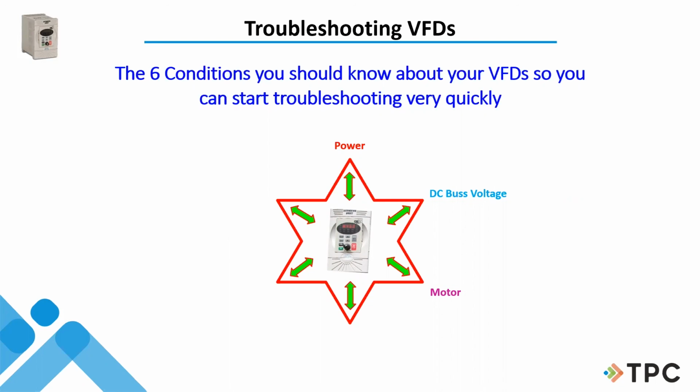And just remember, most VFDs do not like a megger. Don't put a megger on the back end of that drive, or you'll ruin the drive. You're going to have to disconnect the motor wires from the drive if you're going to check them at the drive. And don't use the ground on the drive. Use a different ground. Okay, so make sure you know what those are.